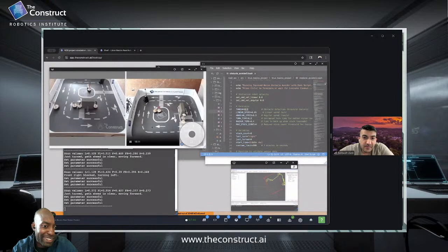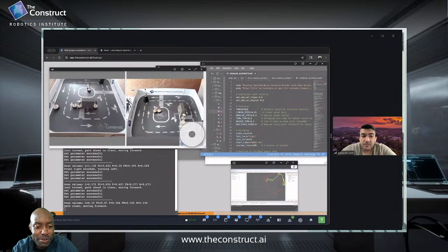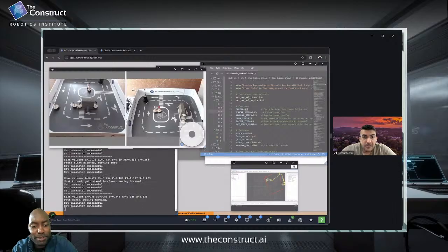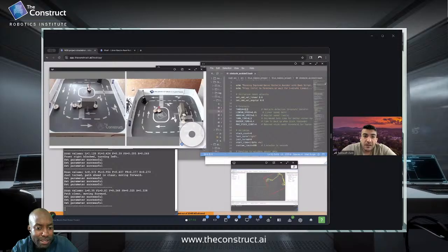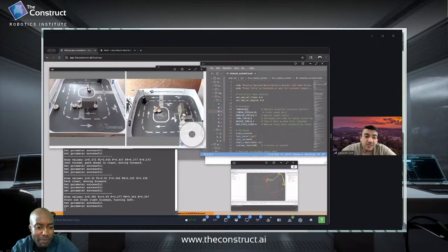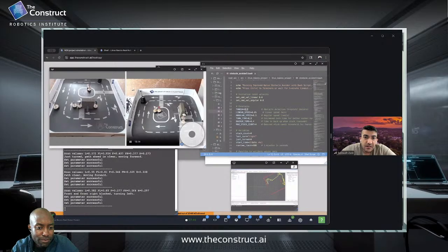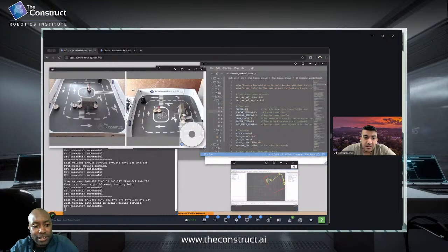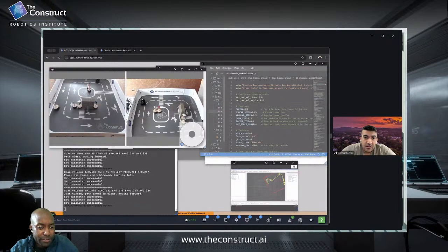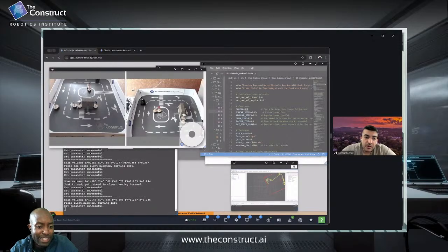Well, I wouldn't say that exactly, but because the speed is generally very low, it's not supposed to be the threshold itself that's actually affecting how it perceives obstacles or when it stops, right? Because for as long as it's within the bounds of 0.1 meters to the wall or to an obstacle, it's just supposed to stop, right? But I think the loop that is responsible for setting the linear velocities or angular velocities is what is not refreshing fast enough, or maybe you're not capitalizing on the distance values that you get.